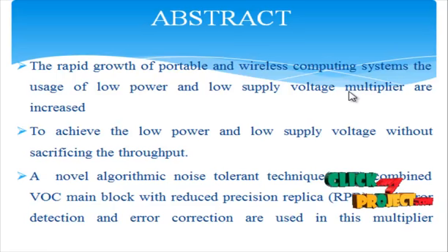The system makes use of partial product weight analysis to find the approximate computation vector for a more precise RPR design. The proposed fixed-width RPR multiplier not only performs with higher SNR but also with lower circuitry area and low power consumption. In order not to increase the critical path delay, the system restricts the computation circuit in the RPR so that it must not be located in the critical path. As a result, the system can realize the ANT design with smaller circuit area, low power consumption and lower critical supply voltage.